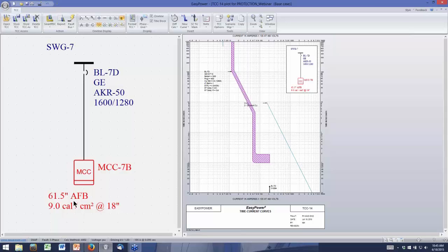And if we went back and looked at the arc flash report, you would see a big decrease in the arc time. I can prove that by adjusting the short time delay here. So if I increase this, you see the arc flash is going up again. So this is dynamically recalculated on the fly as I adjust these settings. So that's a huge advantage when you're doing arc flash studies.